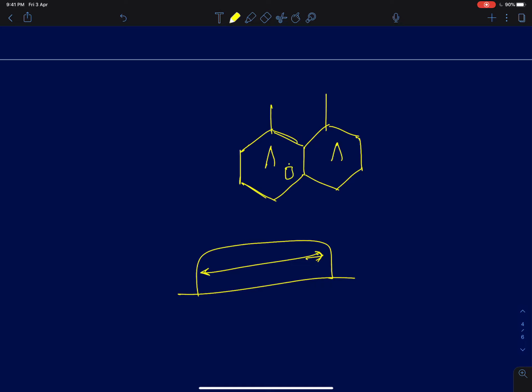Now let's say you have a mobile station operating on a CDMA standard that moves from one base station to the other base station. Again, the mobile phone has automatically computed RSSI, so it knows that it is approaching this base station. But you can have some problems, as we said, whenever you're going to have a handoff: you might have either overestimated or underestimated it. To avoid that, in a CDMA system they can ensure a soft handoff by ensuring that the second base station also transmits using the same code as the first base station.